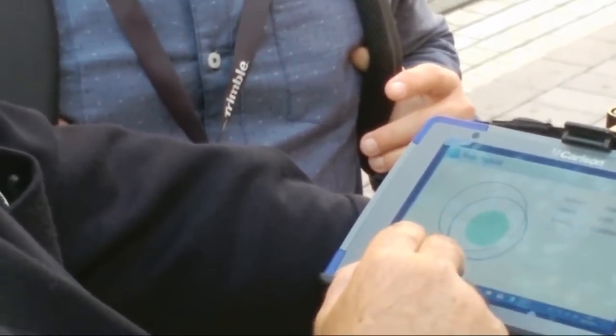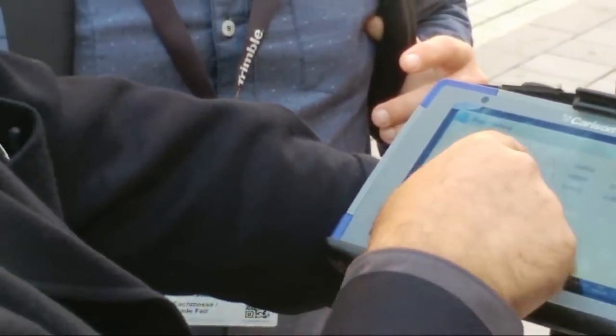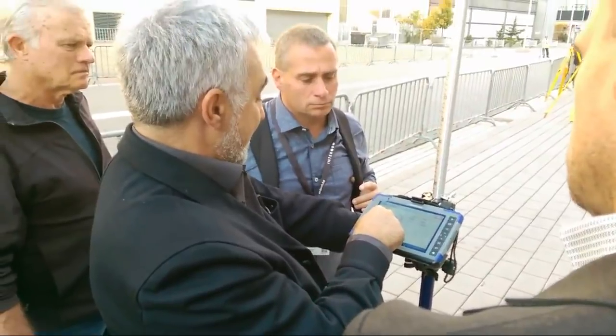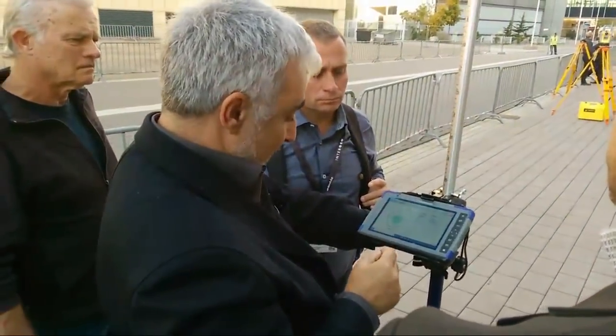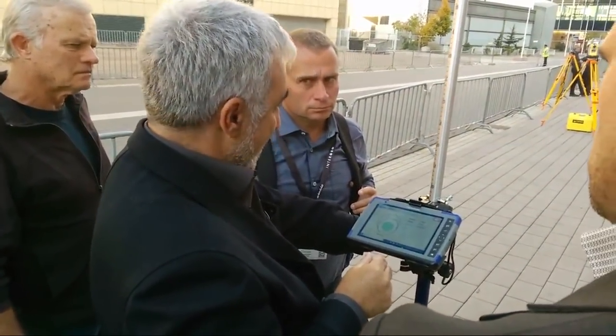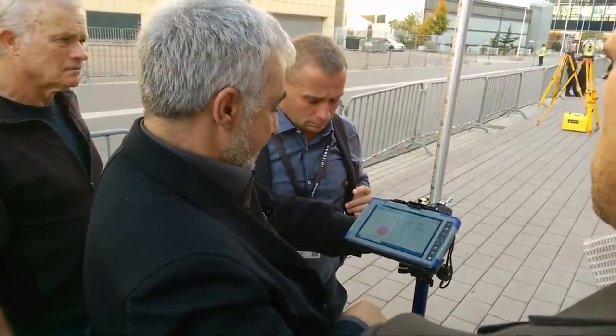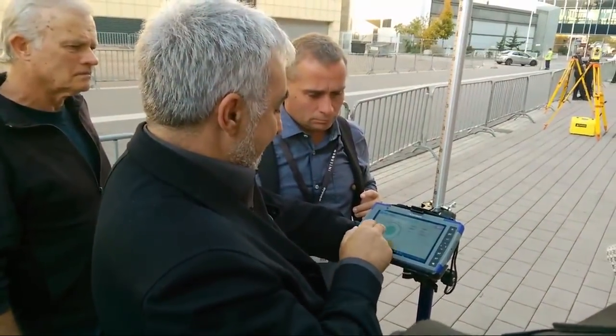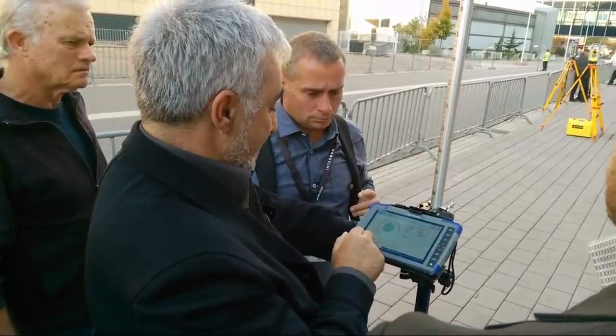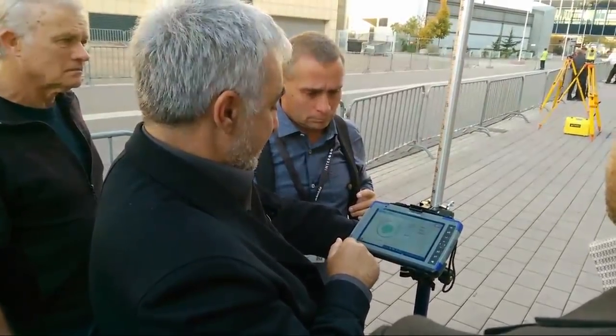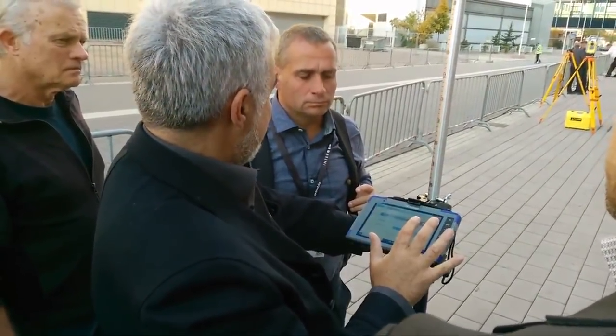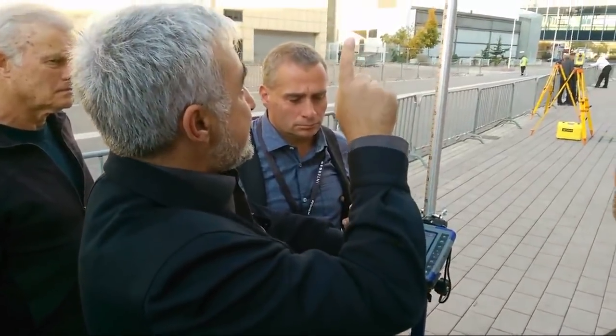But if I say measure, I put it in level within my tolerance. You see, when it's green, I think I set a tolerance of no more than 2 centimeters away from the vertical of the point. So I get it into tolerance to be vertical, and I measure. Reading. Okay, it's done. So I got the GPS and the side shot.